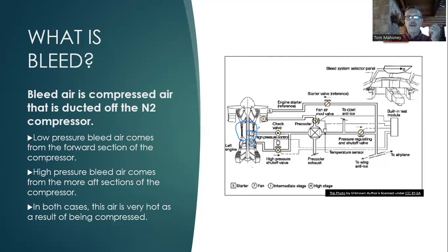And that is where we siphon off the pressure from the turbine, not the turbine, but the compressor. And that pressurized air would flow down this tube. And in some cases, we would use high pressure bleed air coming this way and joining again with the other air in the pneumatic cross sections, pneumatic tubing.